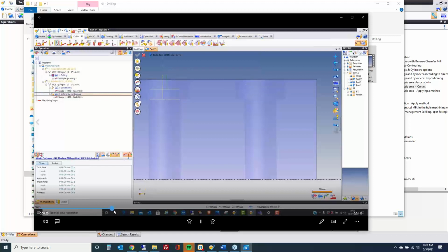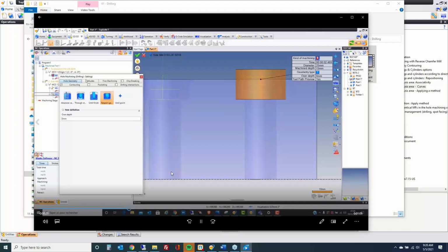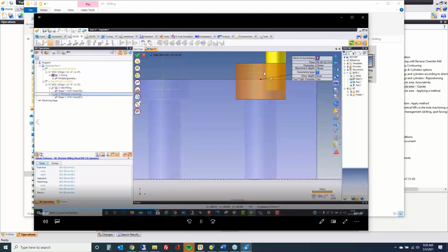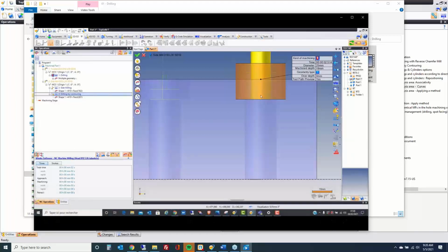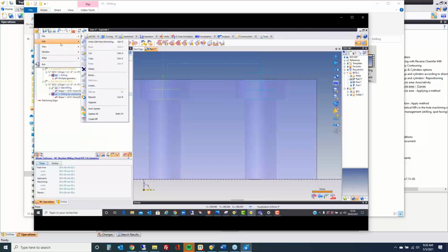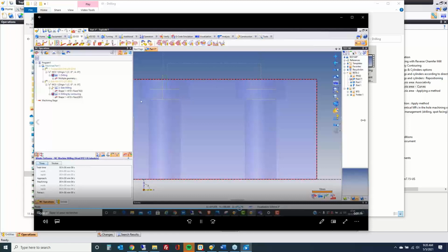Let's go. So we're having a look at the contouring right now. You can see the extra pass. So this was a file open from 714 and 715. So now we're going to upgrade it. We'll recalculate. And now you can see the problem goes away. Okay.